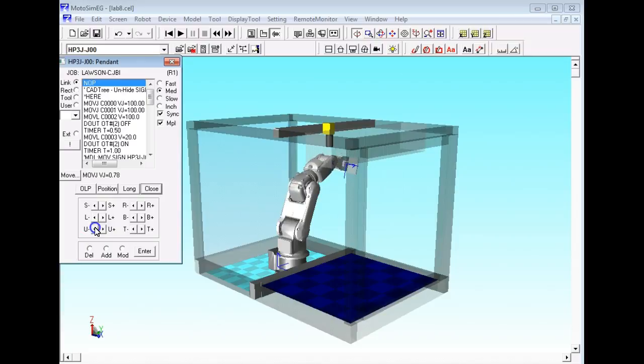And this is the model. Now you don't make the model of the robot. The models of the robots are supplied with the simulation package. But what you have to do is develop the model for the work cell. And then once you develop the model for the work cell, you place the robot in there. And you teach it just like you would teach it over there. So you have different ways you can jog it, which we'll talk about.